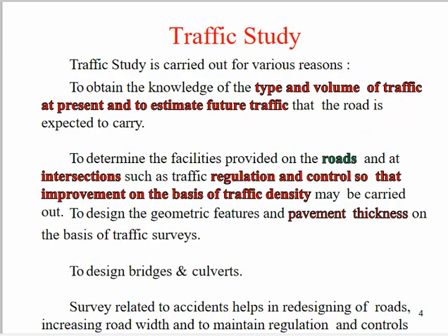Next, traffic study. The traffic study is very important as far as the use of the roads is concerned, and it has to be carried out for various reasons. First is in order to obtain the knowledge of the type and volume of the traffic at present, and then to estimate the future traffic that the road is expected to carry. Knowing the present scenario, that is what actually is the density of the traffic on the road, and forecasting it for the near future can help in order to design the road as well as to have necessary controlling measures that can be taken on the roads.